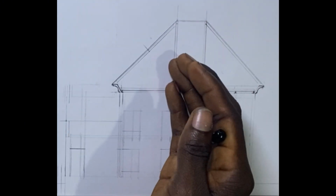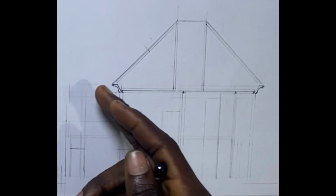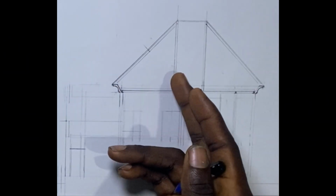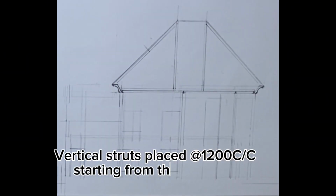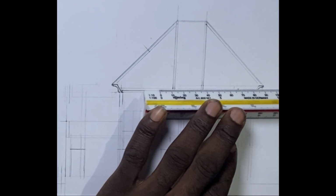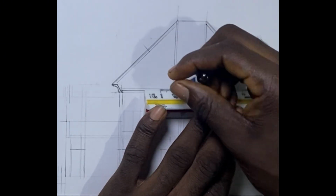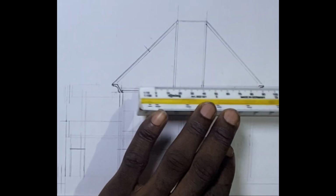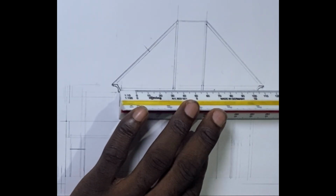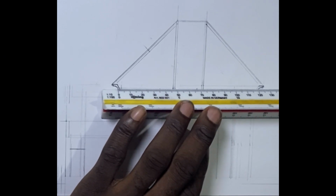Then at this side to our left, we are going to have our strut, the vertical strut placed at 1200 center to center. From our king post, we take our measurement of 1200 at its center to center. Repeat the same for other strut members, which are at 1200 center to center.